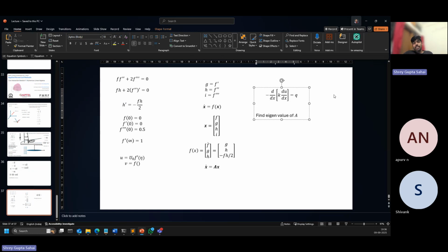What a tensor or a square matrix does is a linear map between two vectors. In your case, stress is a vector and strain is a vector, so the stiffness matrix or stiffness tensor relates stress and strain. As a function, it converts the strain vector to the stress vector.